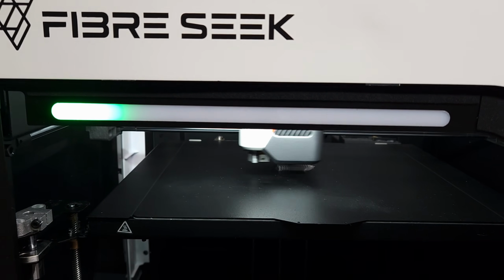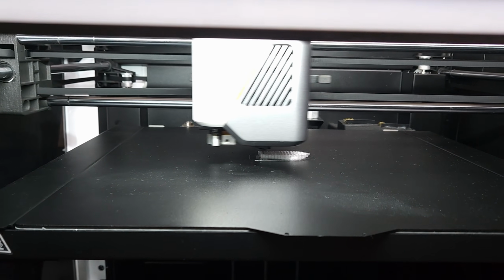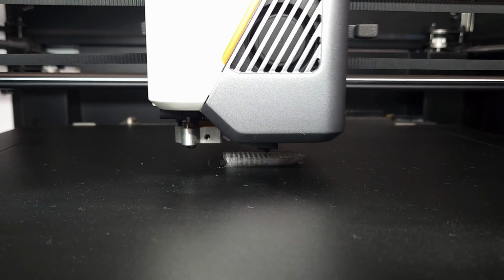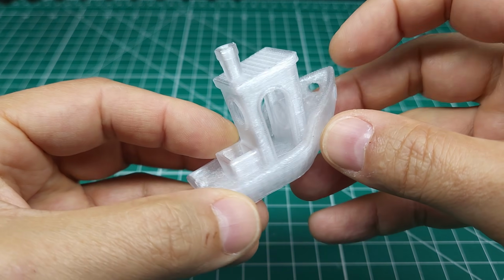All right, we've got the calibrations done. I did have to do a few manual calibrations as well. I'm not going to show that because it might not be the same, but let's go ahead and print the included Benchy. We're printing this in PETG from the right-hand nozzle. Right now, PETG is the only profile they have, but in theory, we can use any filament we want with this setup. As you can see, it looks pretty good.